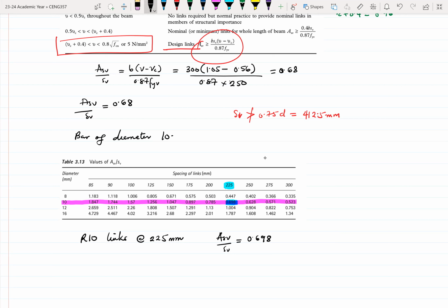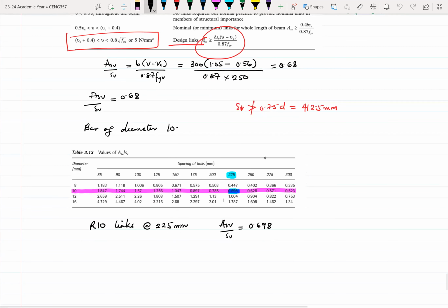It goes up to a certain point where shear is critical, because there are some parts of the beam where shear doesn't really play a significant role in terms of the failure that is likely to occur, especially towards midspan. Towards support, shear is critical. Towards midspan, bending is critical. So what it means is that you would want to have more shear reinforcement towards the support than towards the center.